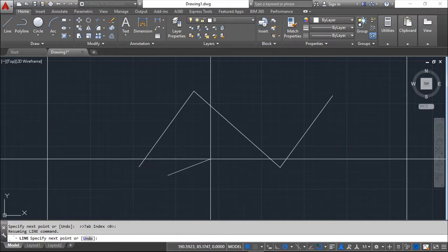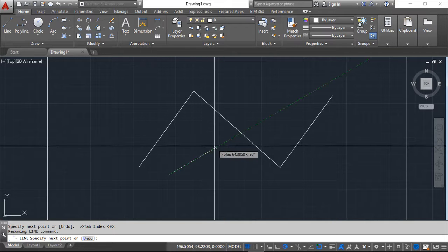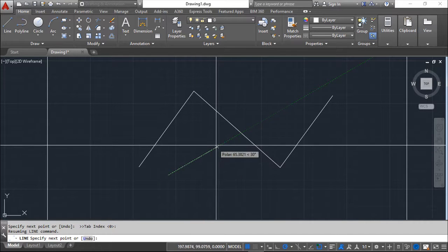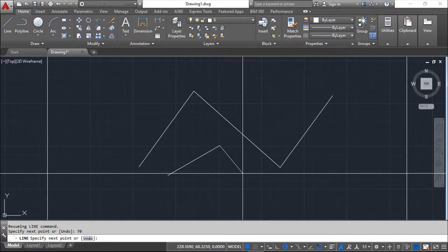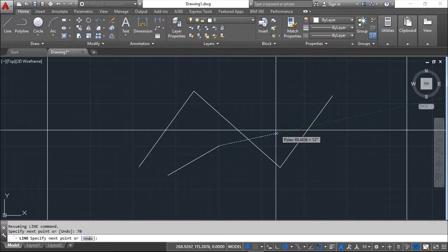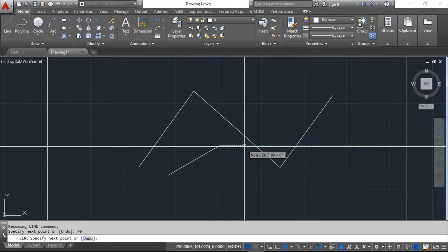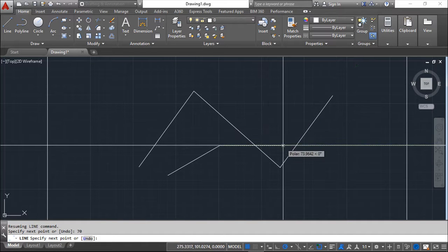So when I have one of the directions highlighted, for example the 30, I have a first point clicked, and now if I say for example 70, the system will measure 70 units from the first point in this direction and click. Okay, and I can continue to use this. But if you see again, the 0 degrees are measured on the same position, the 0 angle to the right.